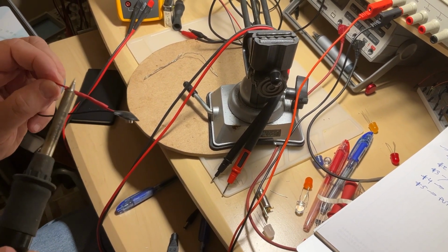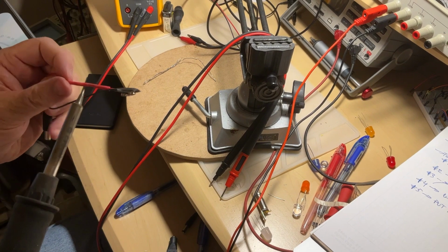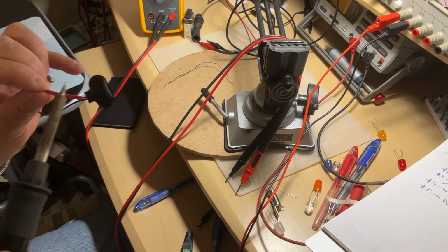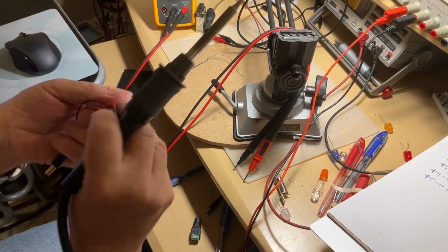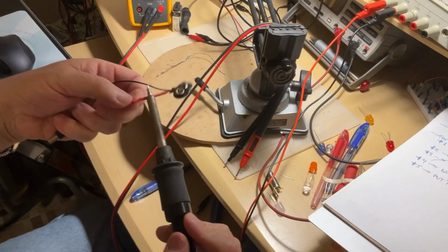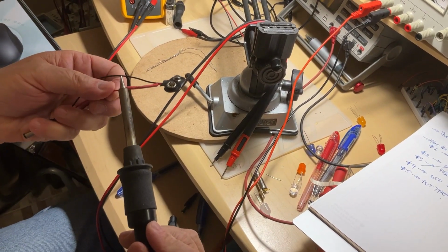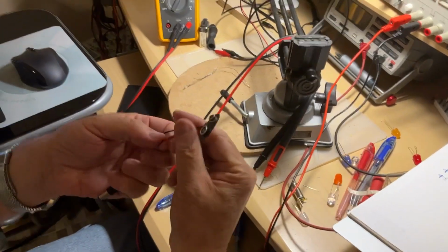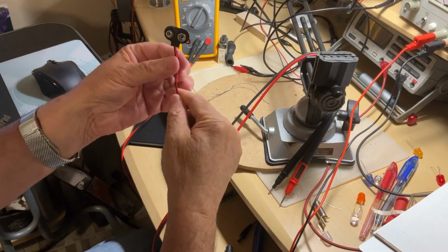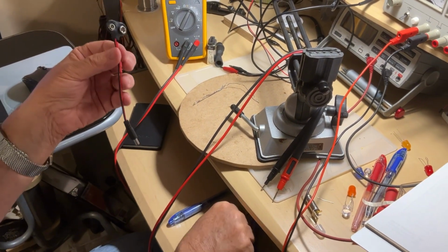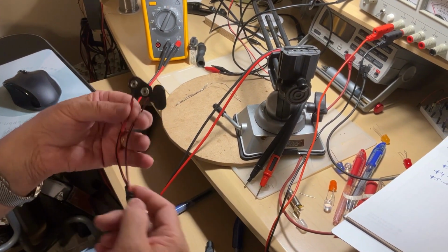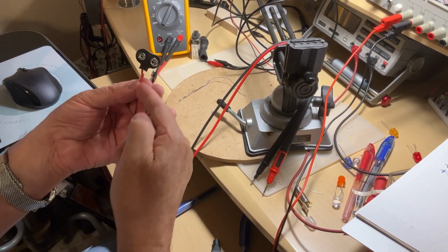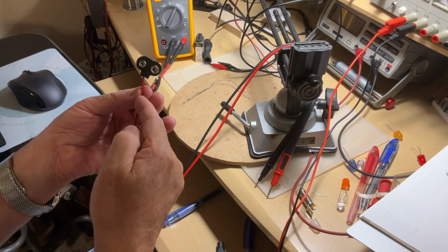So the tube is going to shrink down, because I don't want an accidental touch over the soldered terminals, the two terminals of the resistor. Okay, it's good enough. So now it looks similar to the original, but it's actually not the same, because the trick is that somewhere on the red wire I connected a 1 kilo ohm resistor.